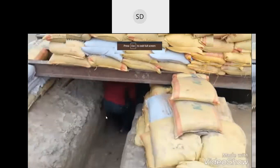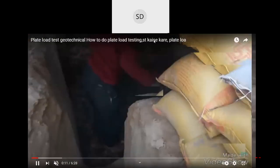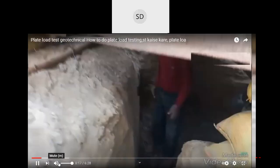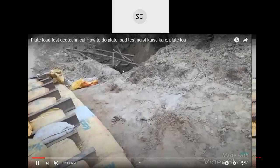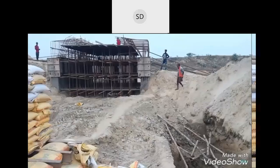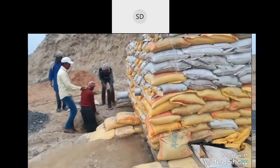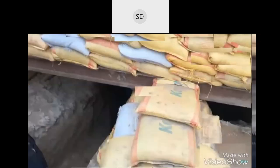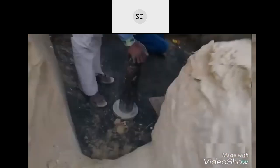See, this is your plate load test assembly. Basically that is the loading frame, and loading is applied over there using some sandbags. So you see the loading frame. Now, this is the plunger through which your load would be applied.